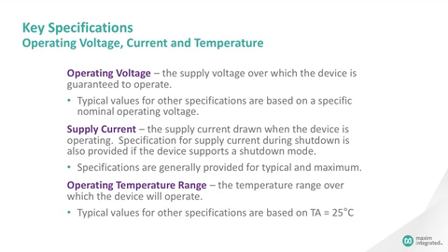Other important specifications include the operating voltage range, power supply current requirements, and the operating temperature range. Many available temperature sensors have operating voltages in the 3 volt to 5 volt range, and it is not uncommon to find operating ranges that extend below 2 volts as well. Operating supply currents can range from a few microamps at low conversion rates up to a few hundred microamps. Some sensors are designed for excellent accuracy over a wide range of temperatures, while others are optimized for best accuracy over a limited range, such as near room temperature.